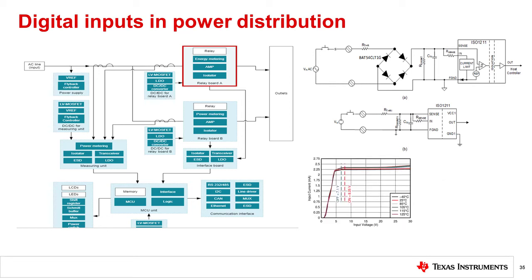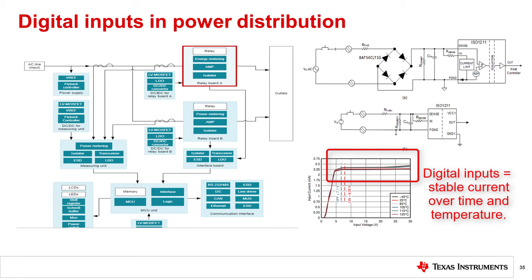Isolated digital inputs offer a solution to this issue with the use of capacitive architecture, which does not have the aging issues of CTR or LED efficiency. Because the isolated digital input offers programmable integrated current limits and threshold voltages, input current is held constant, resulting in lower power dissipation and longer operating lifetimes without the negative effects of LED aging.